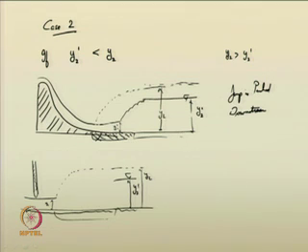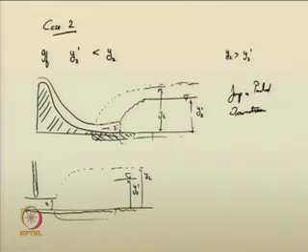So, if the jumps are pushed like this, you cannot appropriately design the thing. We do not know the length of the jump also, and proper protection may not be there within these particular portions. So, it can cause erosion of the bed. If it is considerably pushed downstream like this, the entire bed can get eroded. So, you need to find where the location of the jump occurs. Using proper control measures, once again you can provide the jump wherever the stilling basin is being designed, that is also quite possible.